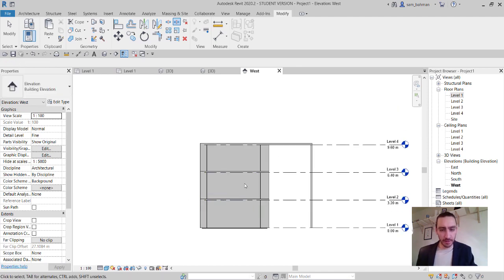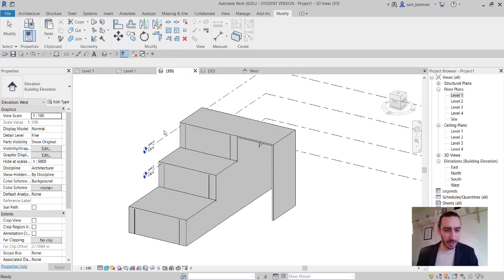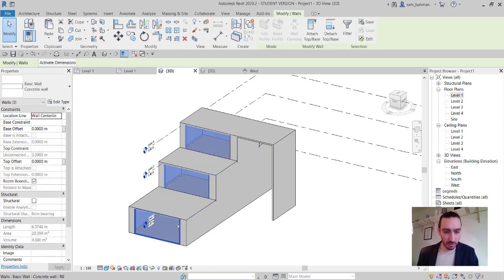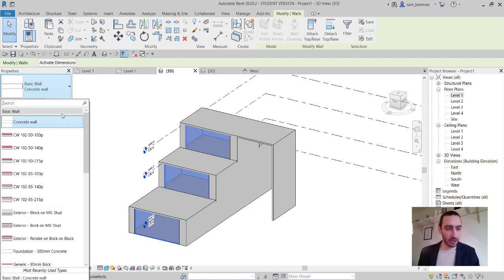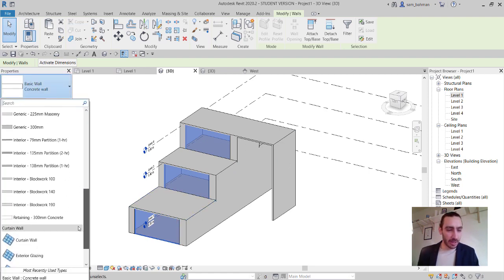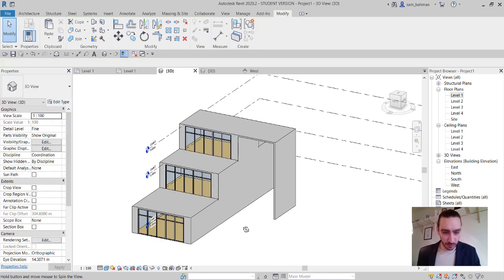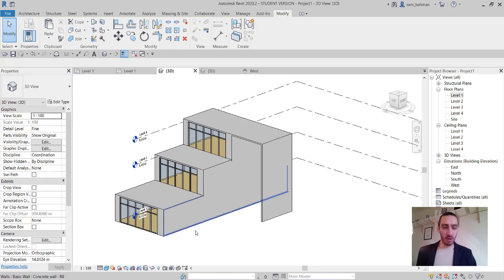All right. So simply gonna get back to the 3D view, and now I can choose these walls with just simply holding the control and make sure that these walls are gonna get transferred to the storefront walls. So as you can see, this side is all done.